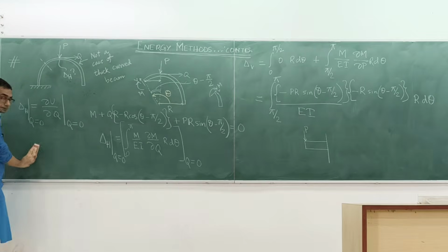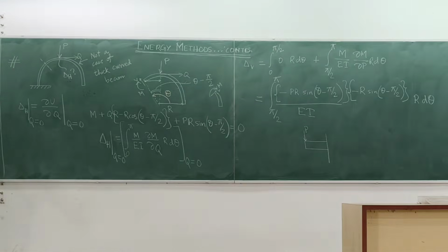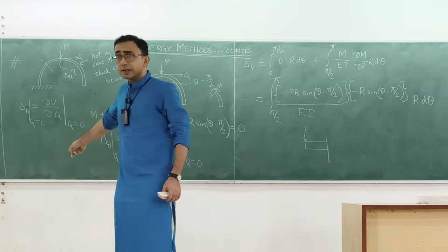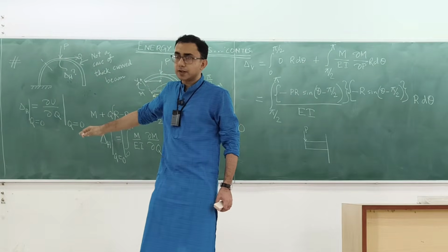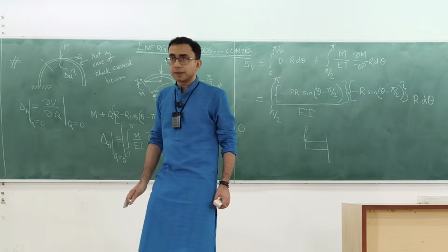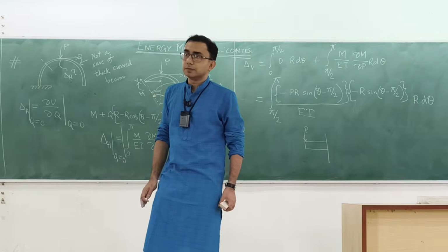But in the last diagram, you made a curvature. You were told that in curved beams, the curvature won't be changed much. So you meant the shape only, right? No. This was an extremely exaggerated diagram. I didn't want to go into all of these things. If it is indeed deflecting like that in such a huge fashion, it is no longer under the purview of small deformation. And if small deformation is not applicable, then Castigliano's theorem is also not applicable.